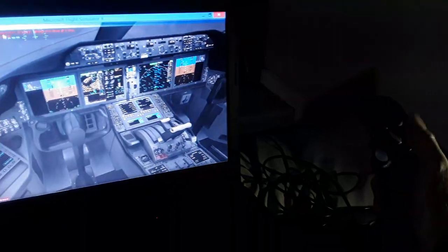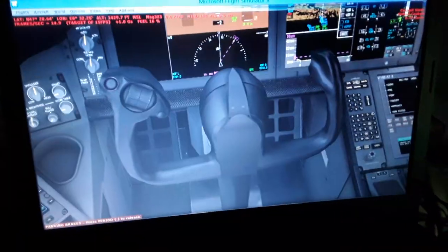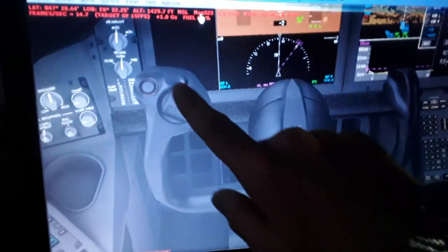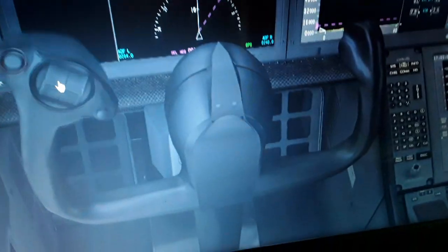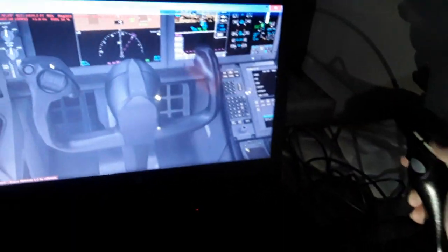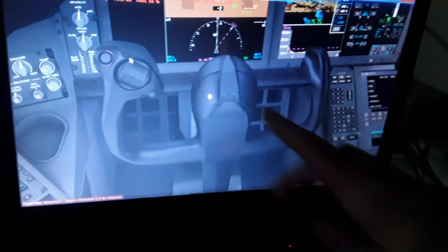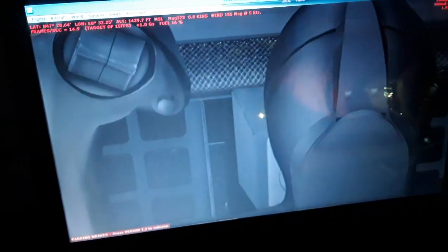So you can use the horizontal trim stabilizer over here of the horizontal tail. You have this control, as you can see. So you can see horizontal trim, elevator trim up. This way is trimming up, this way is trimming down the aircraft horizontal tail. So this is what you do when you press this switch. You press this switch over here, which brings the horizontal tail of the aircraft up and down, as you can see.